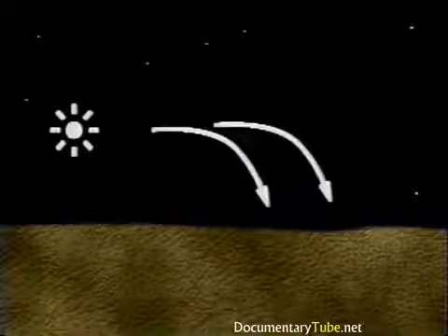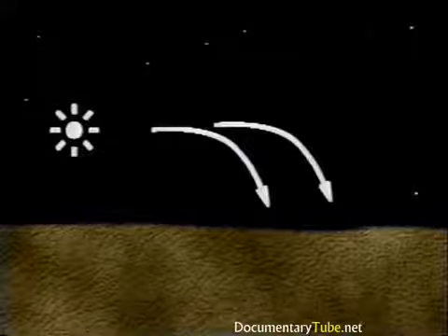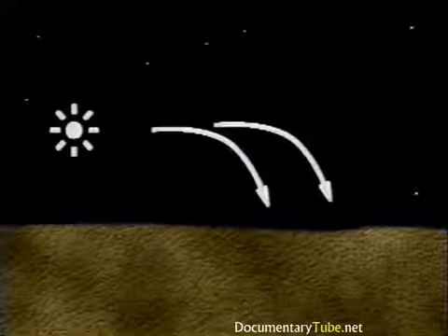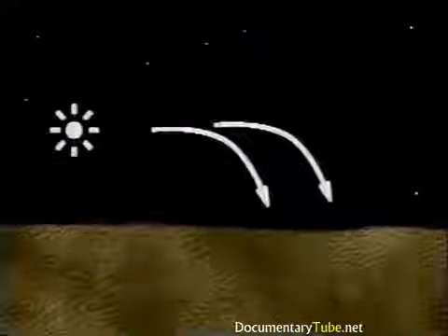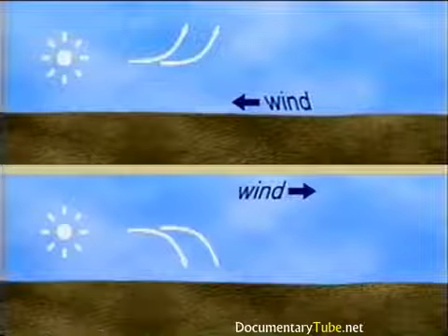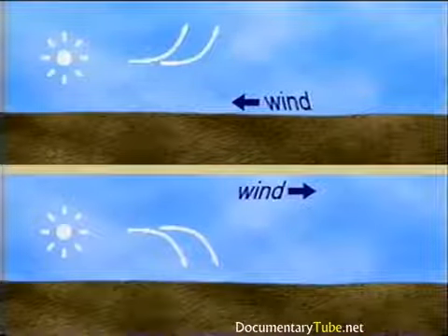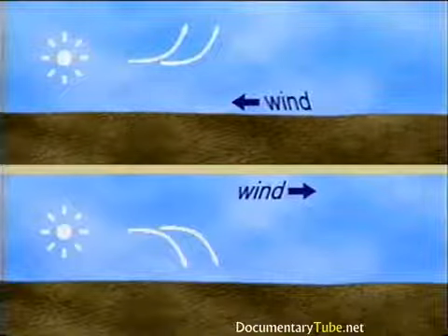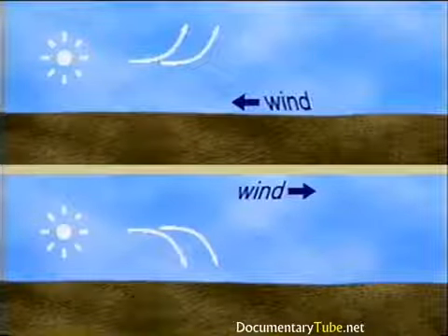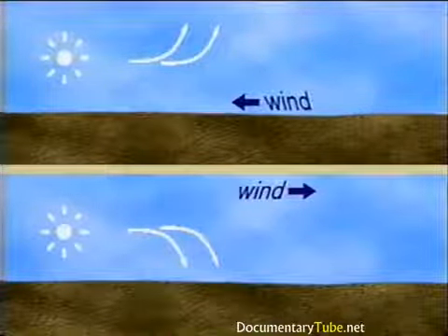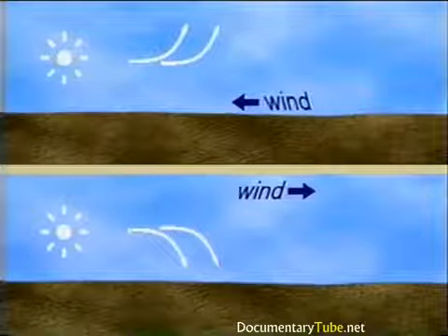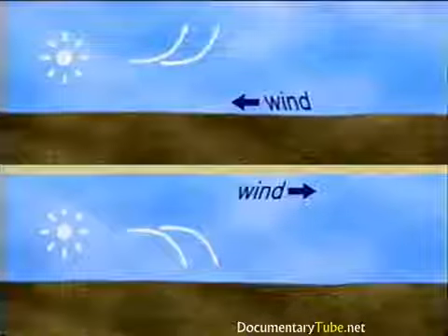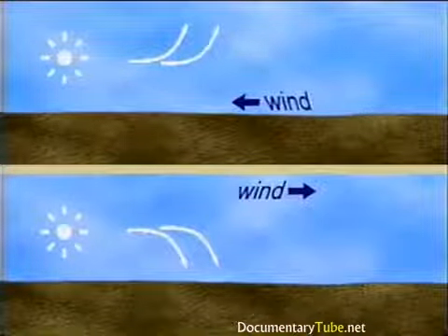Under these conditions, the sound rays bend downward toward the earth. For this case, the noise level increases at the receiver. Besides the refraction due to temperature gradients, wind can also cause the sound to deviate from a straight path. When sound is propagating upwind, the ray paths curve upward as with a temperature lapse, decreasing the received noise level.